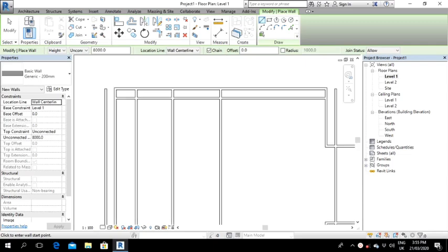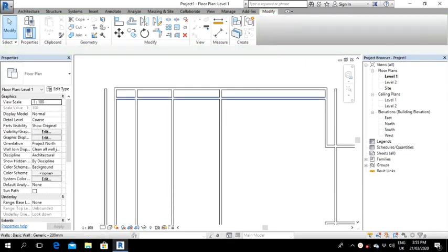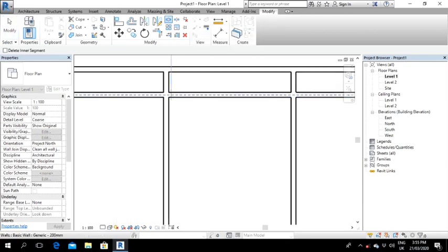Okay, then let's say we have another wall here, for instance. Now if you select this wall, you notice that everything along this line is highlighted at once. But I want this place just from here to here to behave separately when I select this wall. That means when I click on this, this one will not be highlighted and this one will not be highlighted. So what I will do is select split element, push my wall towards this side until you can see this thing showing cuts in the vertical direction. Pick it, do the same for this side, pick it.